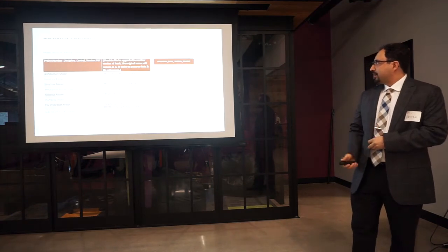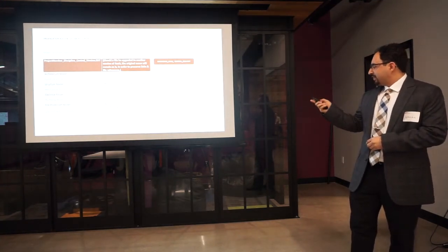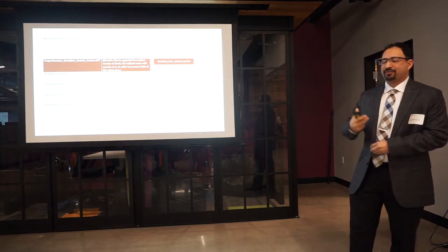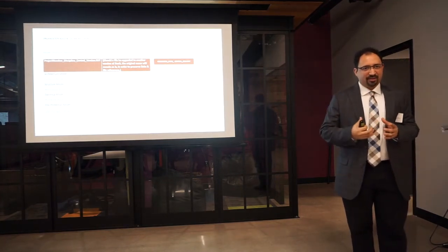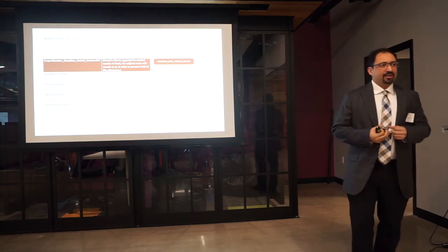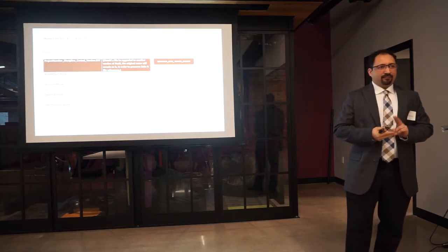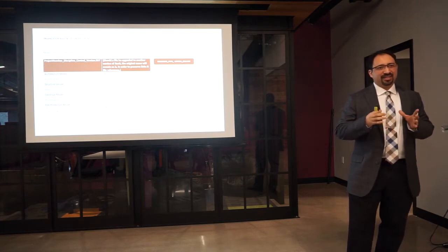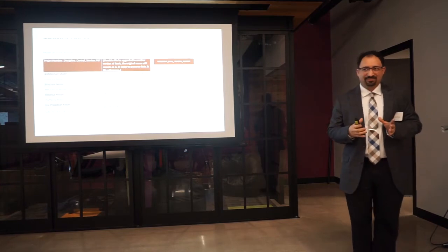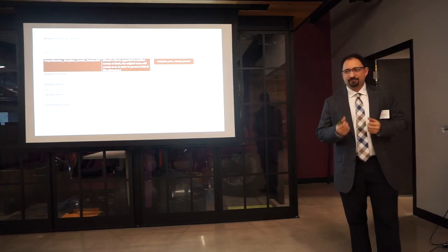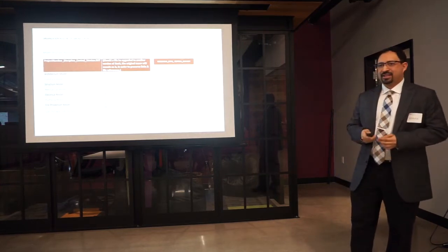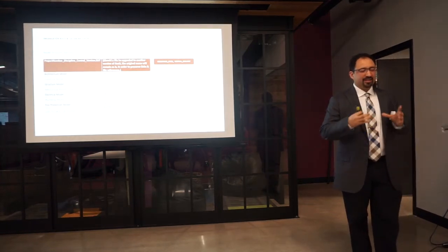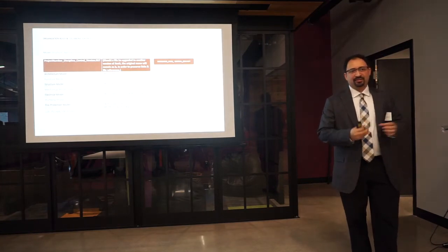To the right side over here this is showing our file structure in the sense of how we link the file to the project. The architecture file in this project had everything. We linked every single model, every single CAD file, so it was one big file. And it was an intense file. It caused a lot of problems sometimes with our computers. But the intent of this was to keep it simple for the client. So when he opened up the file, he had everything in one place. He didn't have to jump around to different files to find drawings.